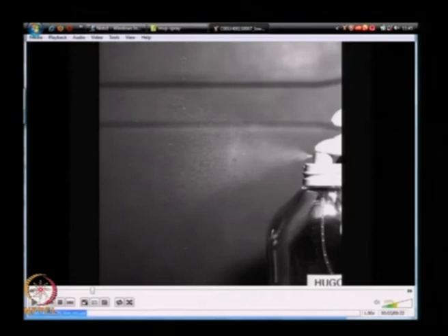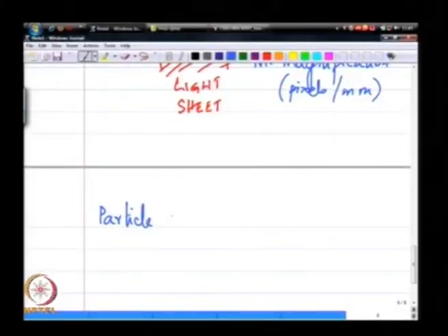This is going to be the case in most of the spray, except in the very periphery of the spray where I see flying drops, or in the middle of the spray where I see bright specks occasionally coming out. These are large drops that I can mark. Except when that happens, most of the spray is going to look like a grayscale image with little dots, and I need to get velocity information from that. In order to do that, we have to move to an algorithm, a technique called particle imaging velocimetry.